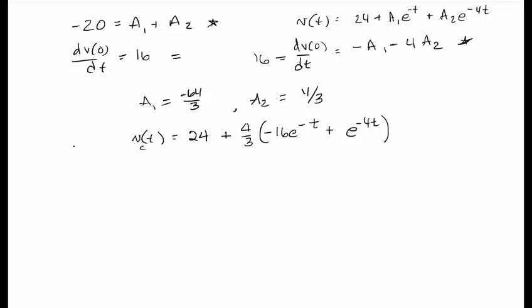So maybe we also want to know what the current is doing in that circuit. That's easy enough to get. The I, which is I in the inductor, but it's I everywhere because this is a series circuit. I as a function of time equals C dV/dt. We have V sub C, so all we have to do is take the derivative of that and multiply by this factor of C, which in this case was 0.25 farads.